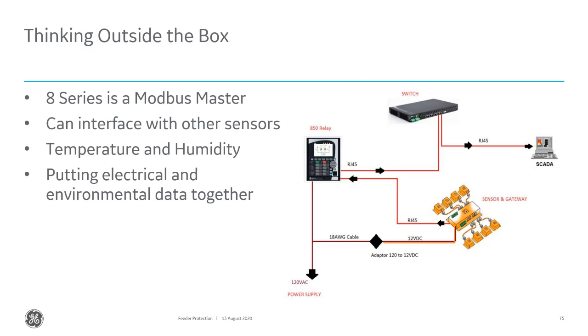And thinking more outside the box, this relay is a microprocessor relay. There are so many other functions. We'll probably do a seminar on arc flash later on, and talk about how to use it to do arc flash protection, how to do zone interlocking protection over fiber optic with GOOSE messaging, and so on and so forth. But I want to highlight something that was way outside the box for me.